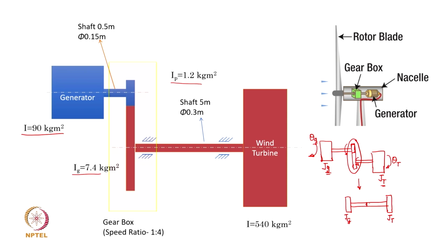Okay. The end of the turbine shaft has a gearing connection. Now, when we try and simplify or transform this to a simple 2 inertia system with a connecting shaft which has its own torsional stiffness, we need to account for the fact that the energy associated with this part of the train should be appropriately accounted for when we convert this model into a 2 mass model like this.